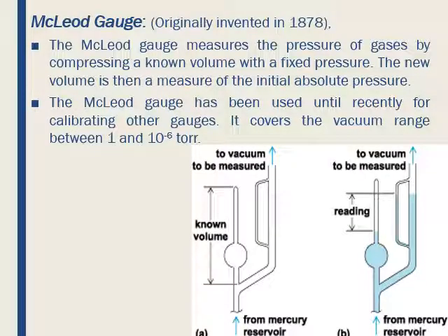Next is about the low pressure measuring equipment. In general, pressure below atmospheric may be called a low pressure or vacuum. Its units are in microns. Very low pressure may be defined as pressure below 1 mm of mercury. Generally, McLeod gauges are specially meant for measuring this kind of pressure.